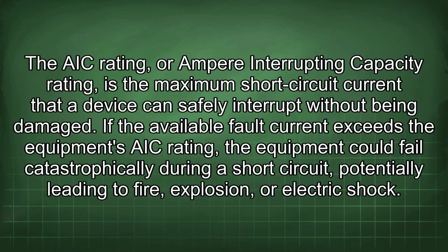The AIC rating, or ampere interrupting capacity rating, is the maximum short-circuit current that a device can safely interrupt without being damaged. If the available fault current exceeds the equipment's AIC rating, the equipment could fail catastrophically during a short circuit, potentially leading to fire, explosion, or electric shock.